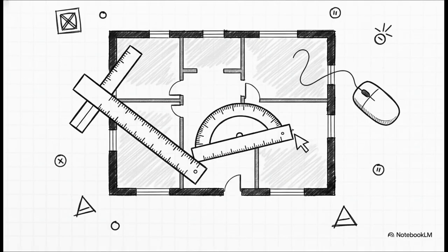During that initial AutoCAD phase, your focus is purely on geometric groundwork. For HVAC, you're mapping out duct layouts and unit diffusers. For electrical, it's all about single-line diagrams and lighting grids. For plumbing, you're looking at water supply lines and riser diagrams.